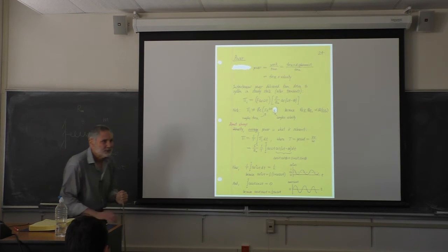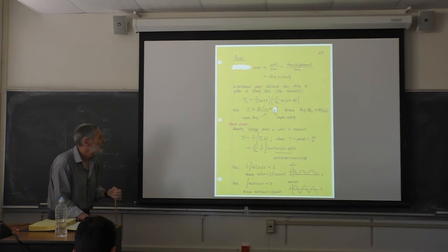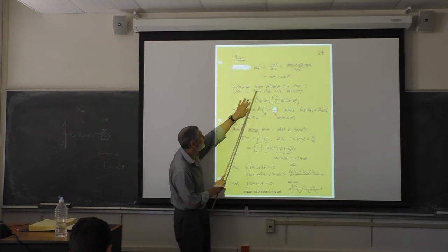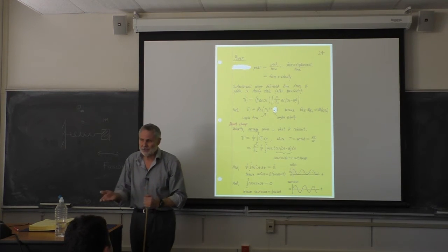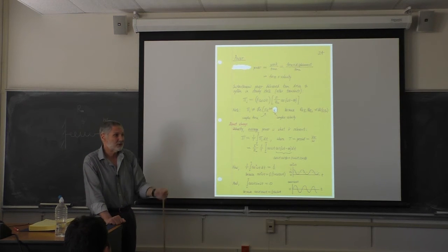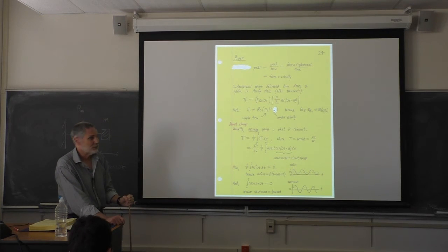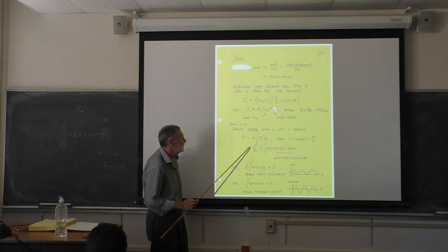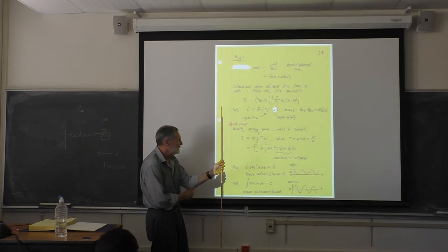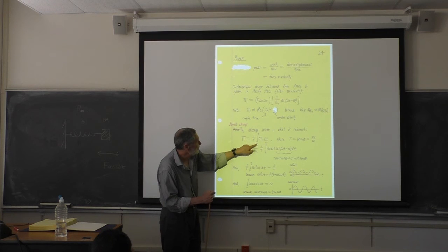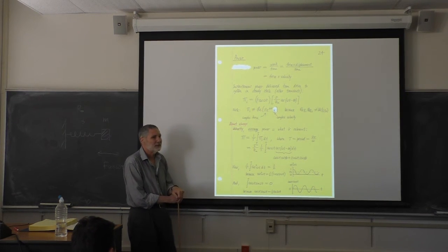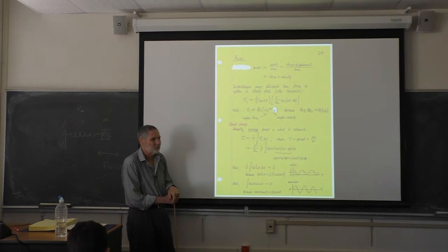The average power is the time average, and because we're looking at steady state motion here, which I should have mentioned, yeah, here it is in the notes, we just need to average over one cycle of the drive or the response. Just one cycle, because this is steady state motion. So we integrate the instantaneous power over one cycle and divide by the period. This is going to be our average power. And that's almost always what people are interested in, what's relevant.